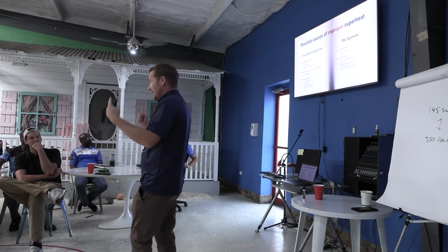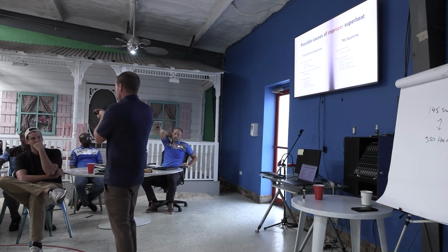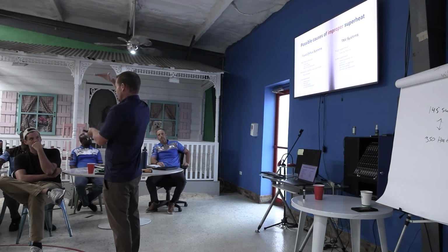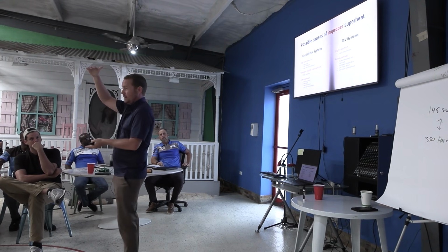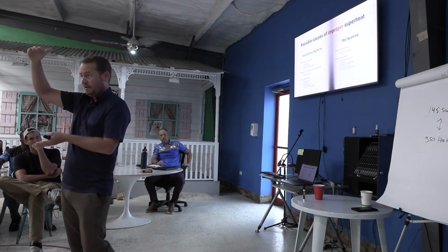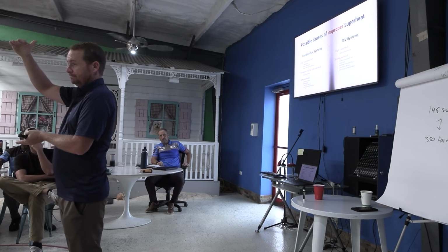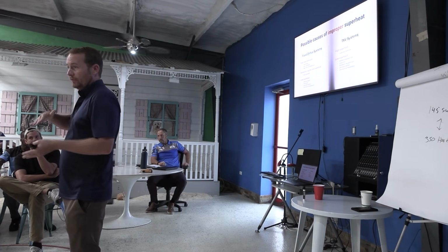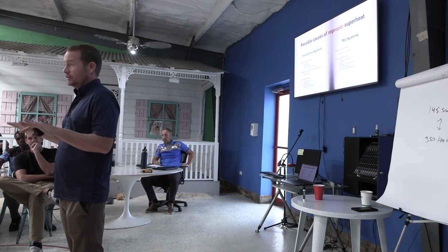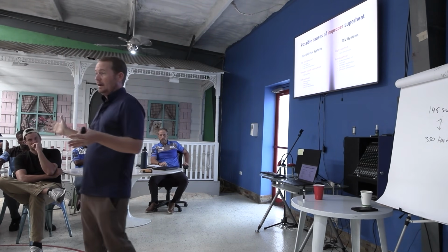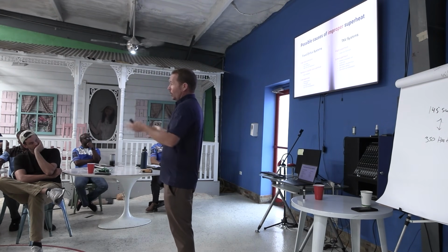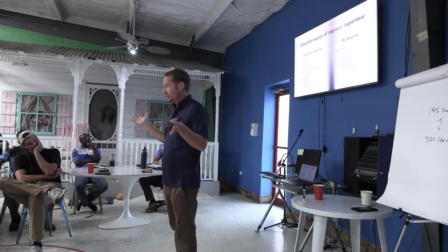And that's where it's really helpful to think about superheat as fullness of the coil. The TXV or electronic expansion valve is modulating the fullness of that coil. It's not modulating the pressure in the coil. That's not its job. Pressure is dictated by load. If you have low airflow, you're going to have low pressure in the coil. If it's really cold in the house, you're going to have low pressure in the coil. You just are. Are there other ways to compensate for that? Sure, but don't do it.